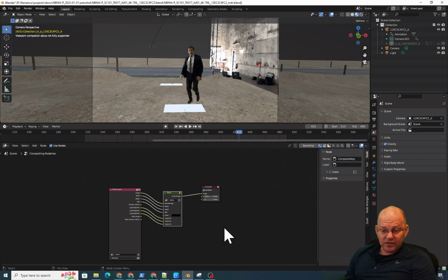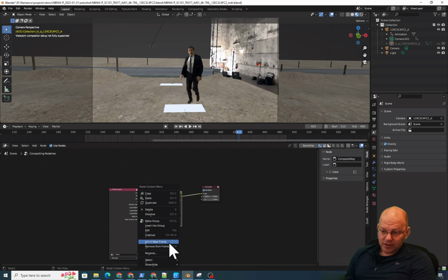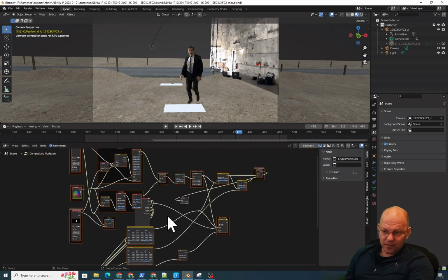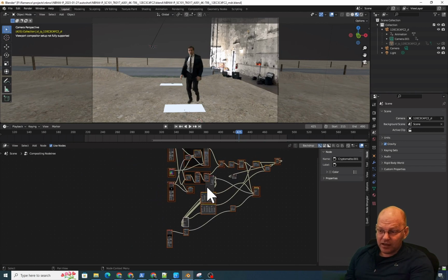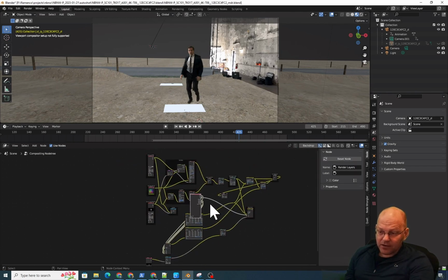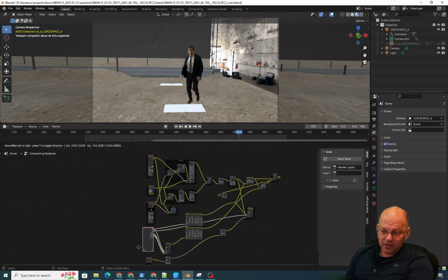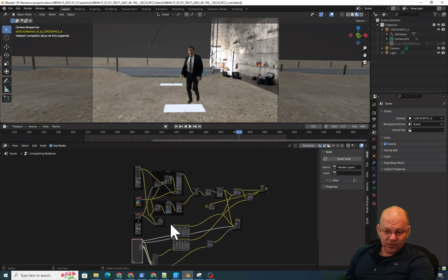We want to dive into the zipline Autoshot node group, but we want to use our magic O button shortcut. So the easiest way is to ungroup the Autoshot group. So we're going to right click on the Autoshot group and choose ungroup. I'll scroll back out with the scroll wheel. So the node tree will expand. The render layer group is in the middle, causing some confusion. So go ahead and highlight that. It's here. Hit G for grab and move it over here into its blank area. And now we can navigate through the comp.